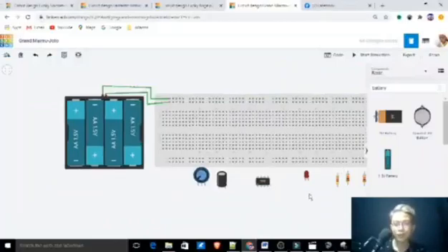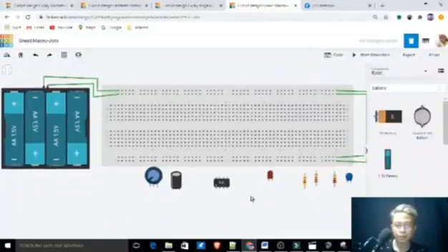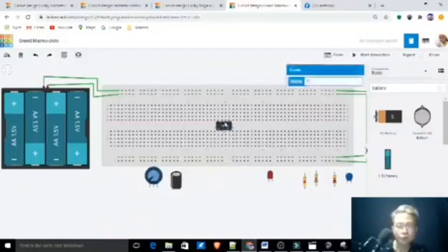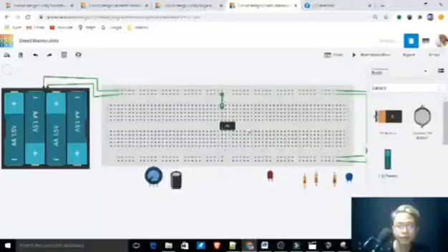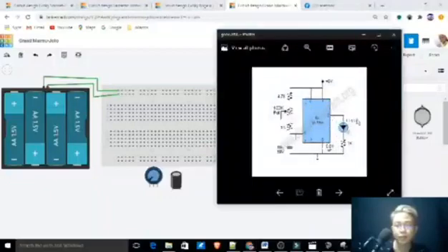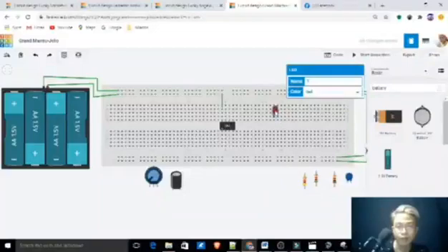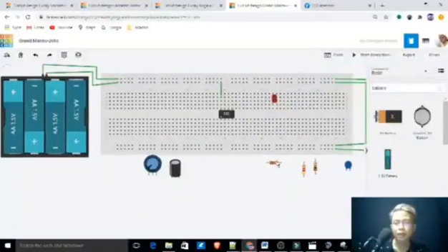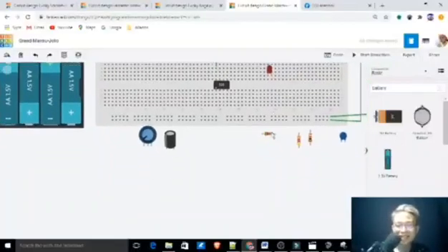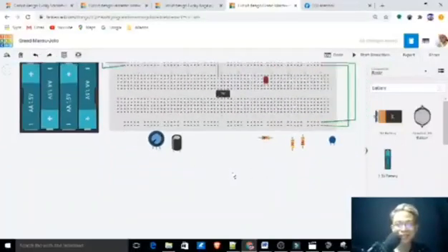So we have to place all of these simple materials here. First, I'm going to place that one, as you can see here, from the pin three to the LED. I'm going to place the LED here, and also this 1 kilo ohms resistor. I have to turn this one. Okay, I'm dragging.